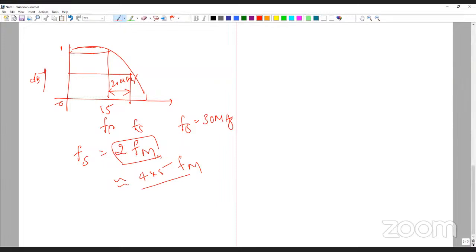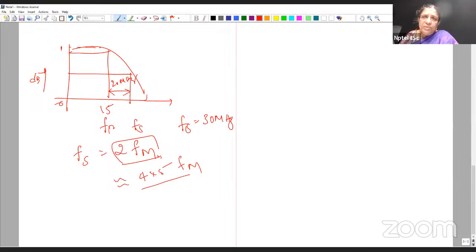Then we need to up convert, like 950 to 970 megahertz. You will be using an interpolation technique, that is upsampling and then downsampling. I think I did not cover in this course how to do that. In one of the ADC lectures I told you that it is sampled at a high rate because we use sigma delta ADCs. And then somebody asked what happens to the noise.